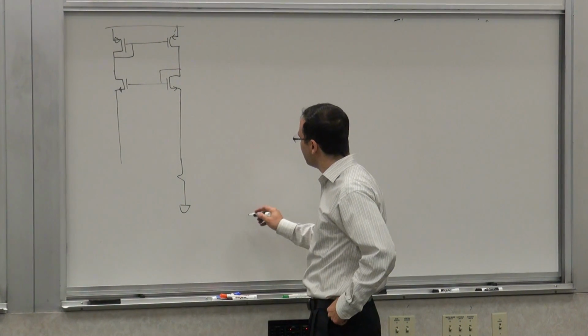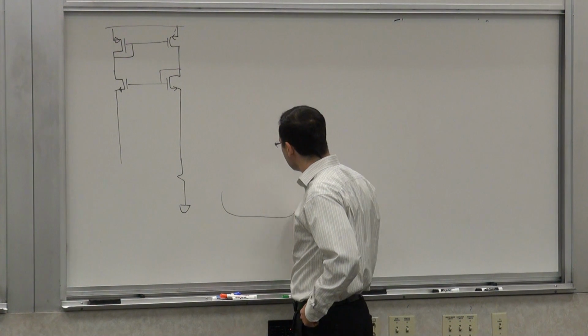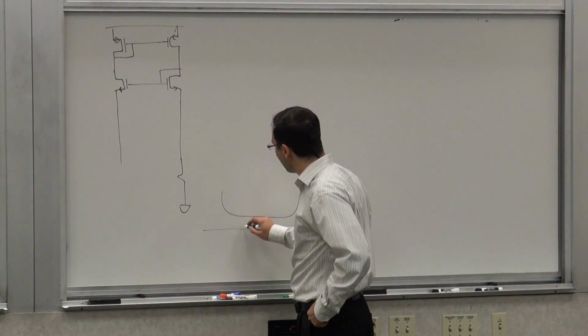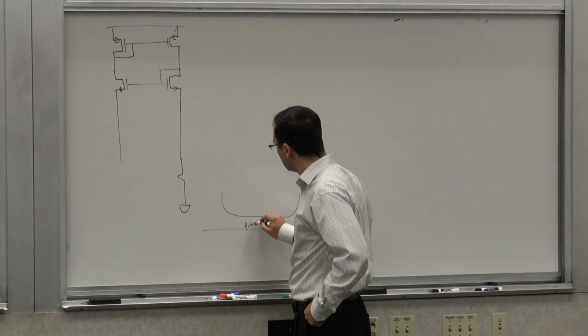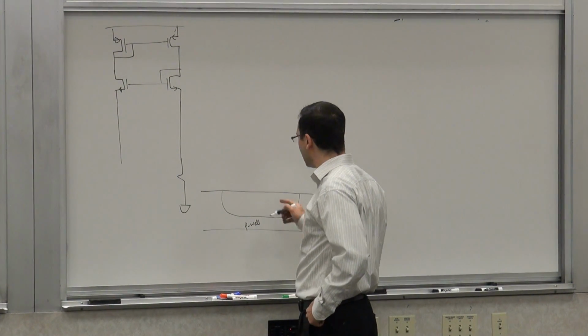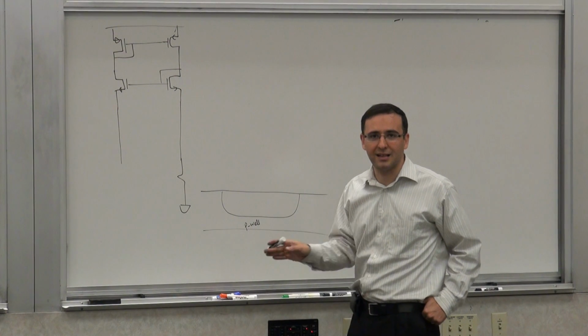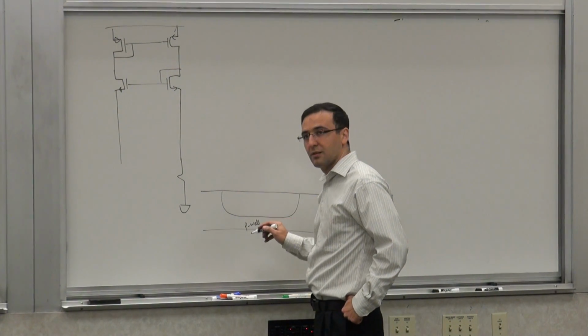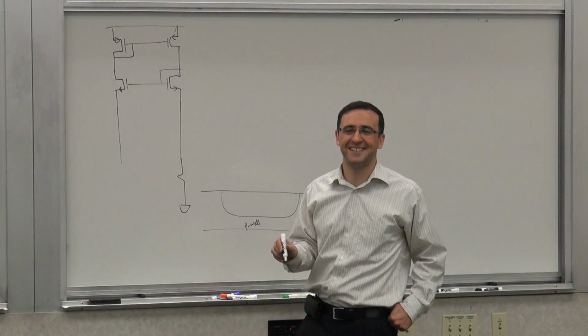But if I want to get a VBE, even if it's like a transistor kind of VBE, I remember I have a P well in a most basic vanilla process. So if you can get it in the most basic vanilla process, you can get it in anything, essentially. What process? Vanilla.